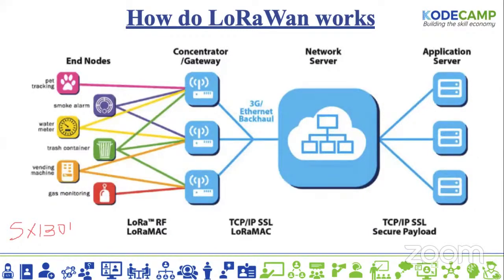It really helps you to maximize both the battery life of the end device and the overall network capability. So it uses something called the adaptive data rate. The adaptive data rate is a protocol that LoRa uses on the network server to manage data rate and radio frequency output from one particular node device to the other.